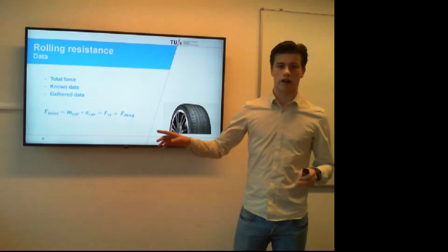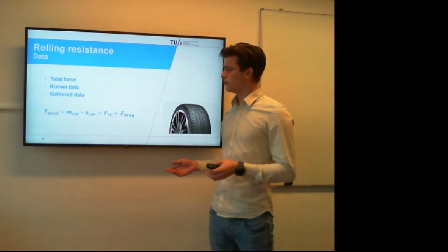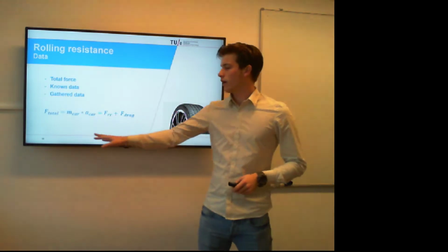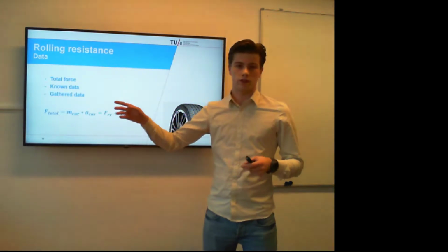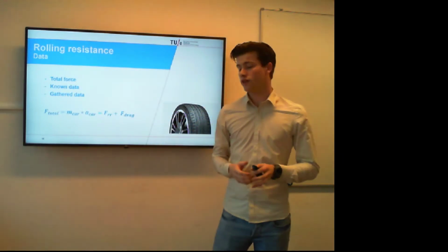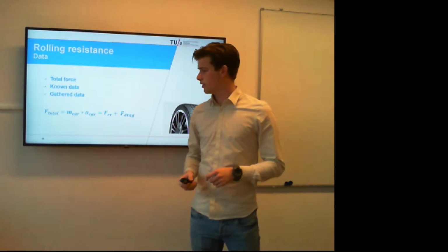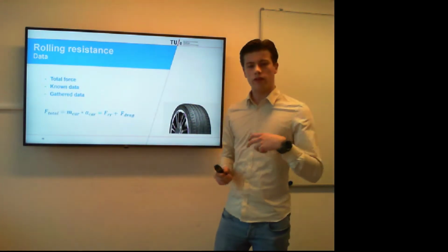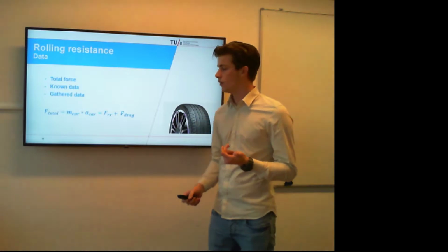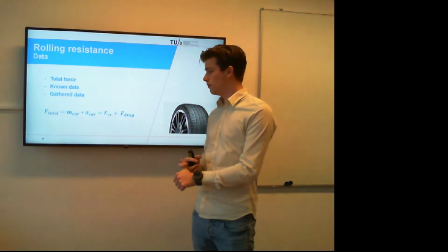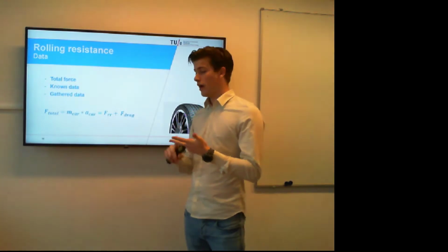The mass of the car can be easily computed with a pair of scales. With that we can calculate the total resistance the car experiences in its deceleration. With the electric motor attached, the total resistance consists of the resistance within the electric motor, the drag force, and the rolling resistance.